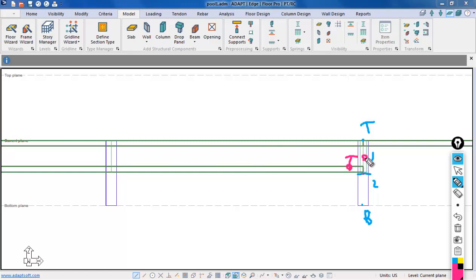If this node of the beam actually is below the mid node of the column, then you could have connectivity problems and this beam really needs to become a wall. But that also imposes some limitations, which are the design strips along the beam.